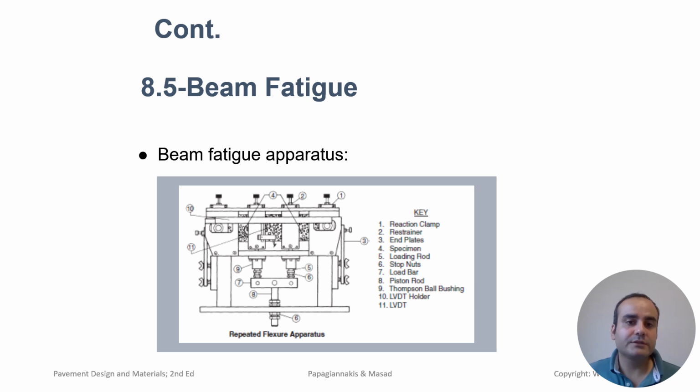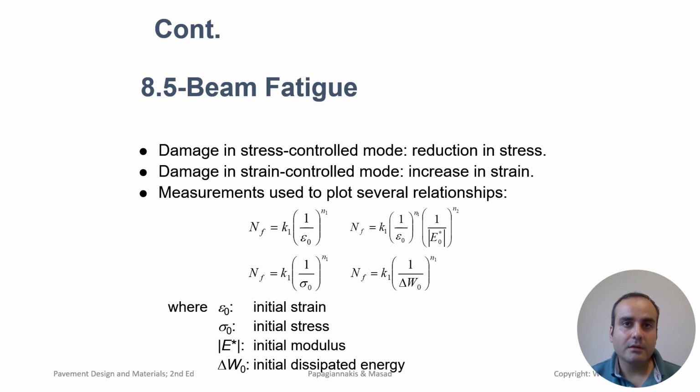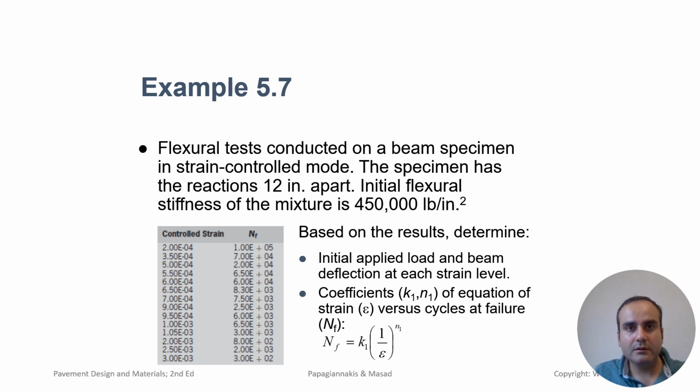This slide shows the beam fatigue apparatus and its different parts. In beam fatigue tests, damage can be determined in stress control mode or in strain control mode, and measurements are used to plot several relationships between the number of cycles to failure and stresses or strains.